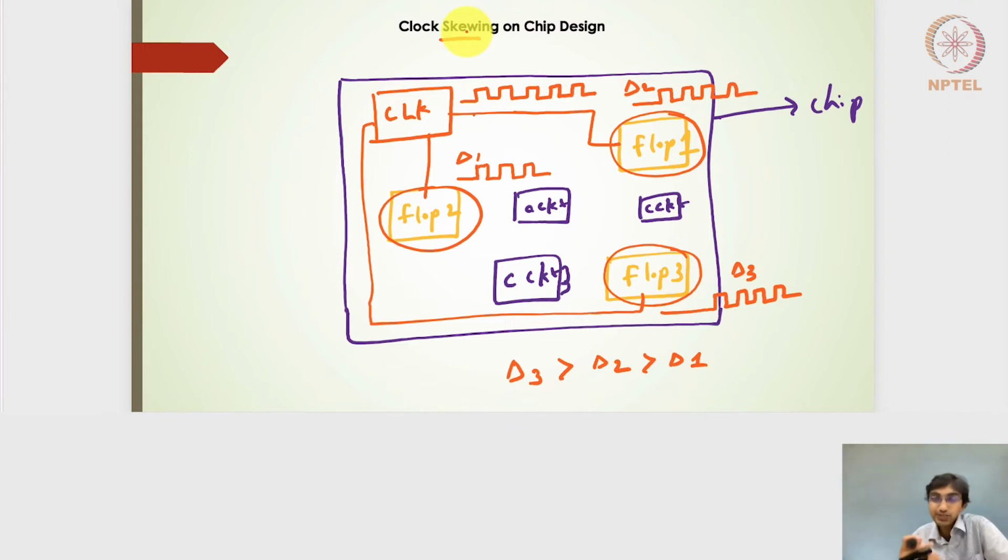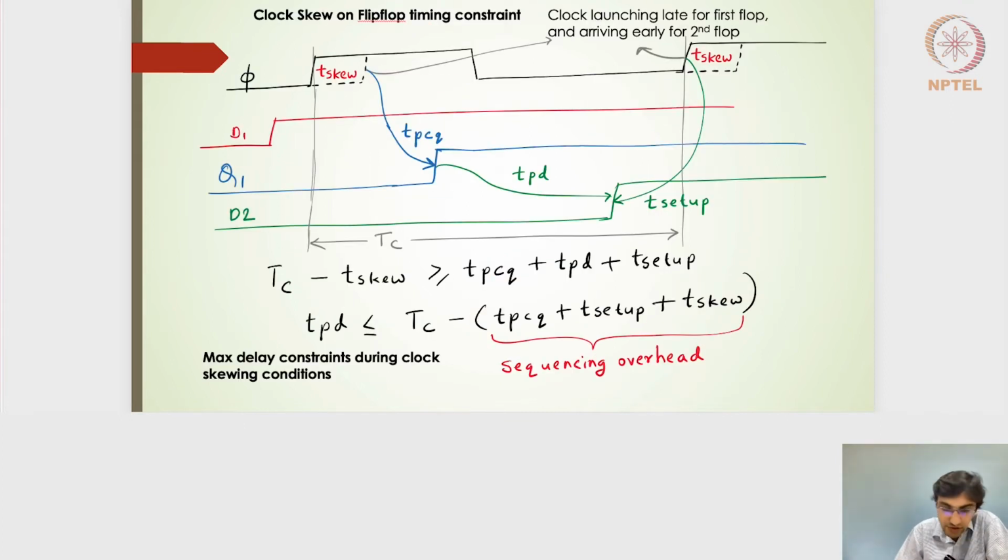Right? So if we are expecting that it should be captured in the second clock, it should be able to capture that. So in that sense, this delayed clock signal is also called a skewed clock or clock skewing, and we should design the circuit in a way that it is resilient to this skewed clock. So moving ahead, let's take a simple example of what you used to do. Let's say we have the, let me draw it here.